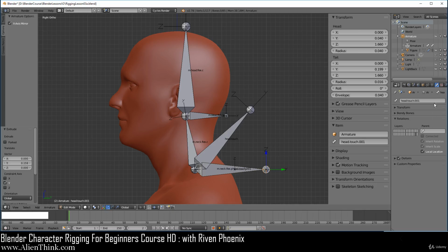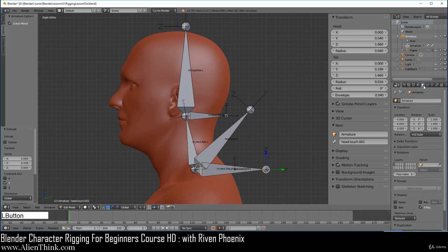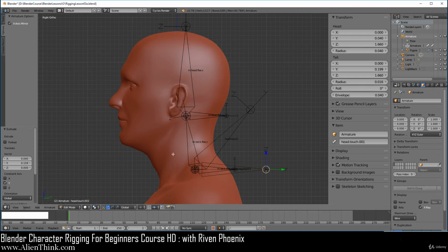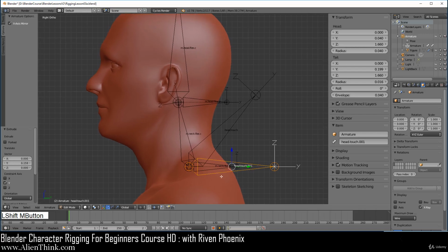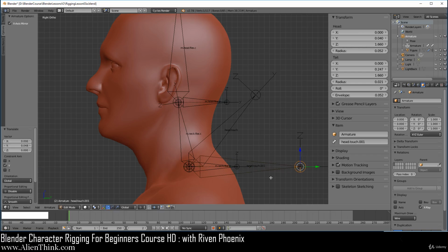What this simply means is that we will have to go to the Object tab and switch this to Wire. So now when we create the module-based system, everything is going to be done in wireframe. So here you can see that when we are aligning these bones like this, we're simply going to be burying bones inside them. That's all this means. Now always keep this in mind that when you align these bones like this, you can always click on the tail and move this bone over here to make room for other bones, right? And later you can move these and tighten them up.